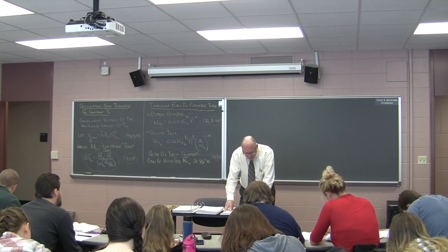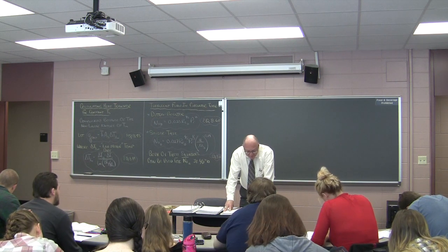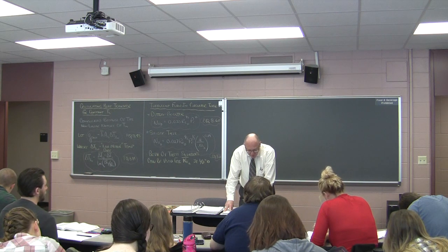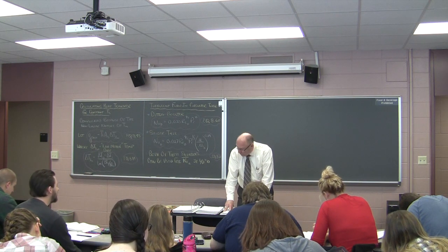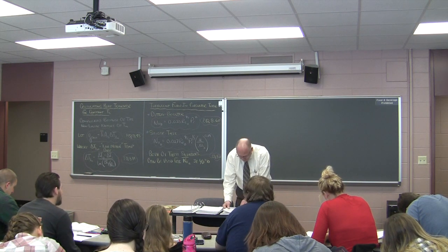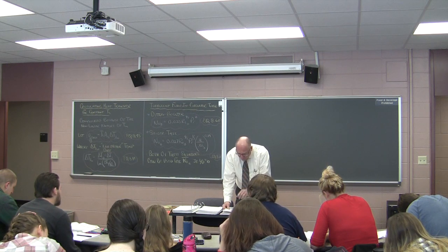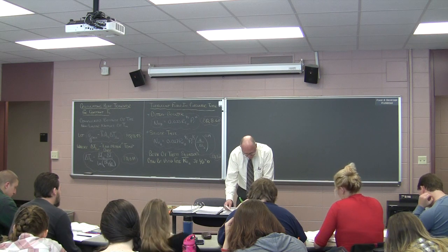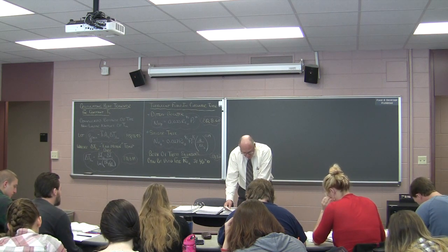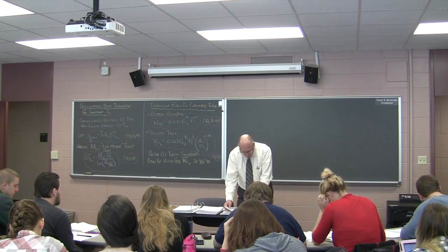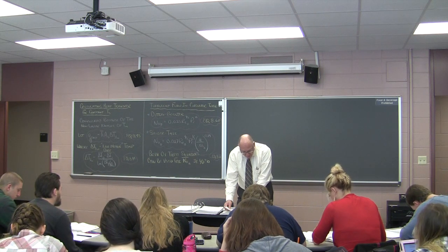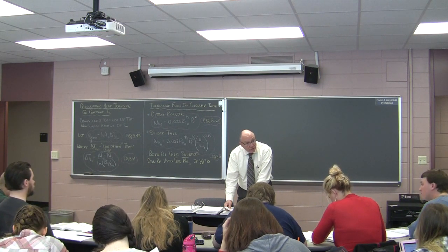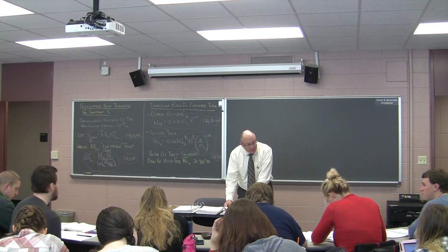All right? And let me just say this. In general, the Dittus-Boelter equation is for smaller temperature variations. If you go to page 516, you will see equation 8.60. It talks in the paragraph above about the conditions which I just went over that are highlighted in table 8.4.